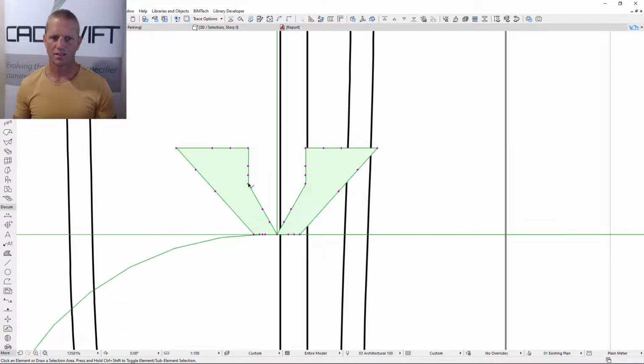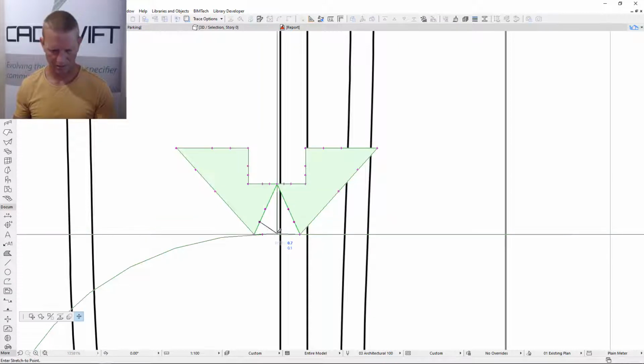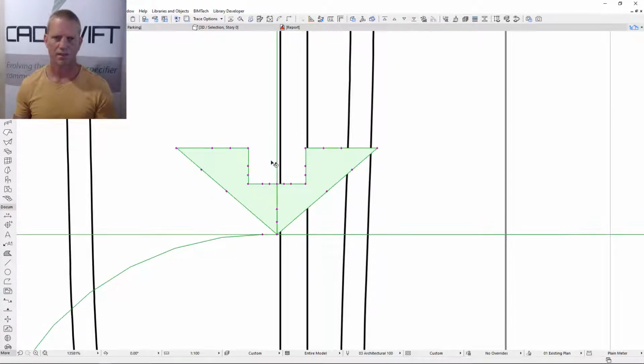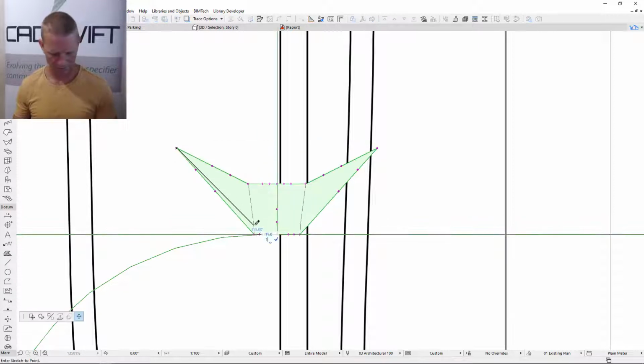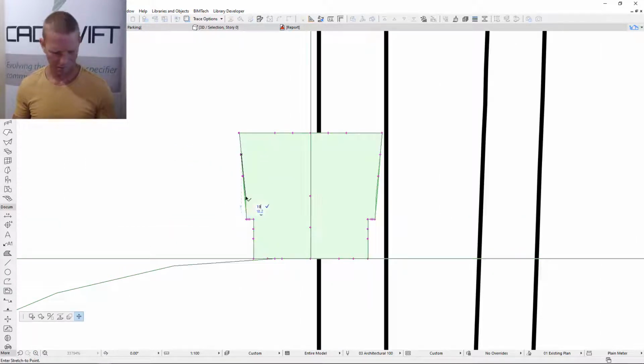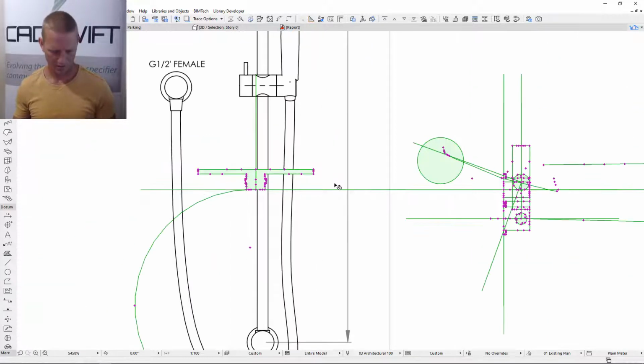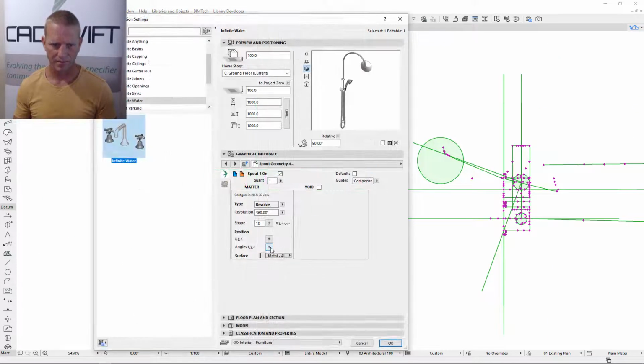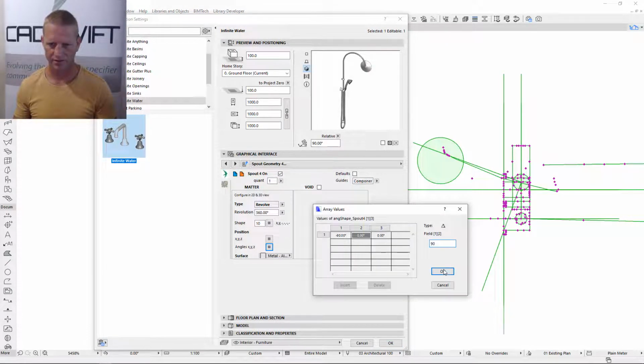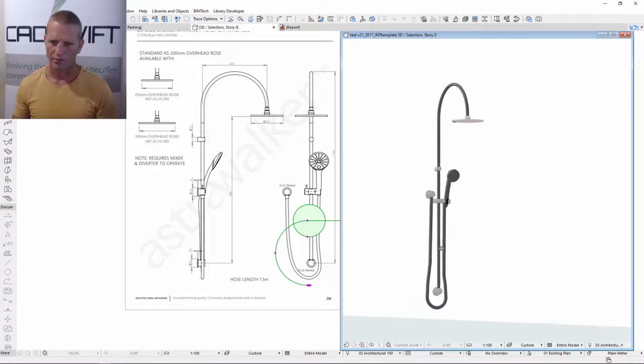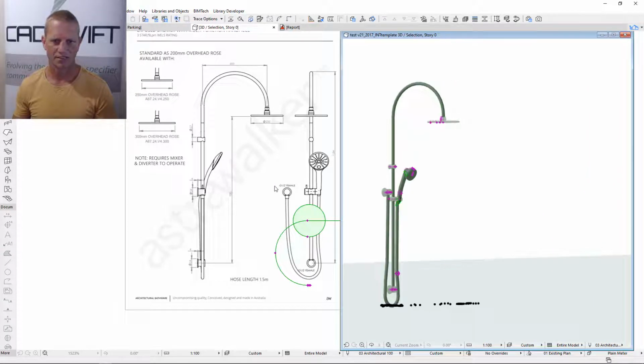Okay, so you notice this doesn't want to go to the 0. There's an order of the nodes in this element, and these elements that are supposed to be out on the edge don't like to be at 0. So what you have to do is basically move these ones up. Okay, go back into the settings, rotate it back that 90 degrees, and voila! So that is basically the same configuration as this element.